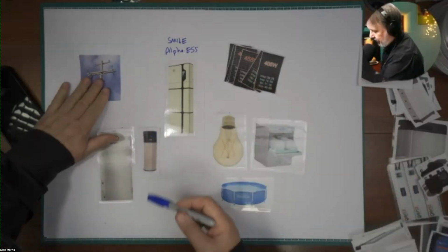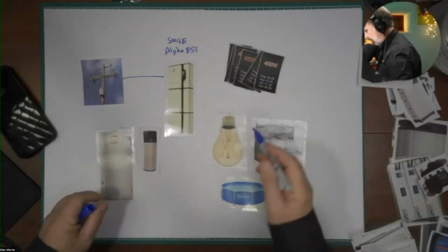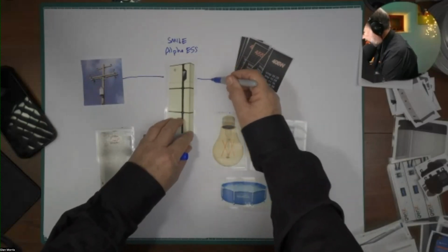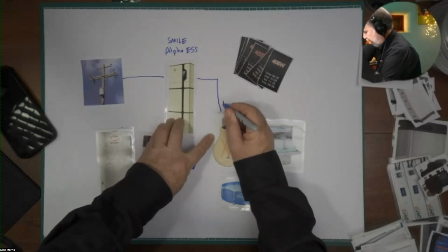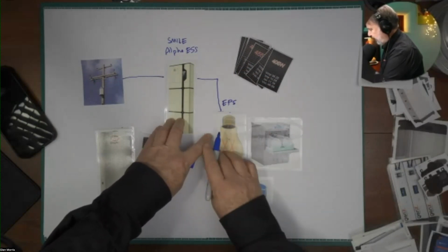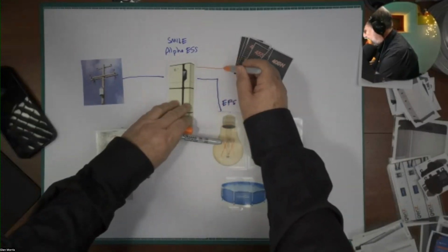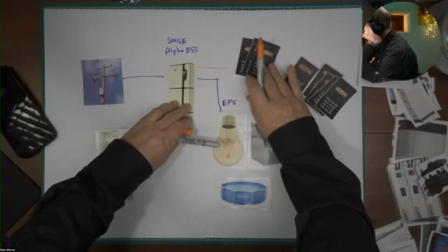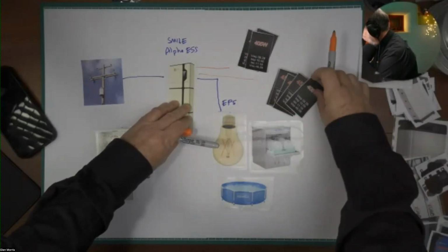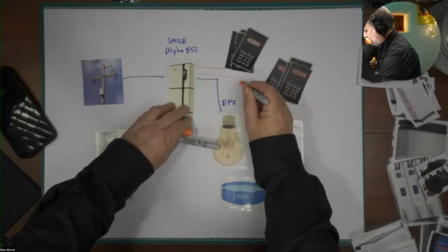So let's draw the lines here. AC power is blue, so we're bringing in grid power. We are supplying through a dedicated backup circuit our essential loads. So we'll call those essential power supply, EPS. So these are the loads that will be backed up if the grid fails. Then we'll have our PV connected to it. Now this is a dual MPPT, so we can have two different types of panels. So we've got some 405s and some 455s, two strings connected by DC. So that's the DC cables here.